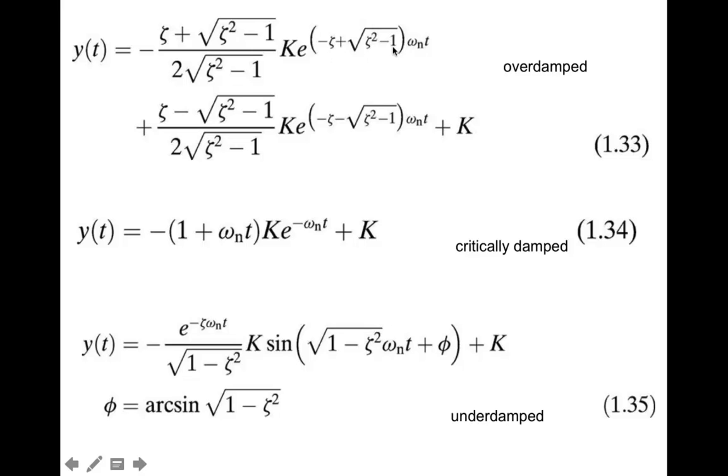So if you look here, this is the damping factor, and the entire thing of this times omega n is 1 over a time constant because this is of the form t over tau. So when you have 2 different time constants, you basically have 2 different exponential decay rate functions. So usually one is negative and one is positive, so you'll have kind of a dominating rise time and then a dominating decay time.